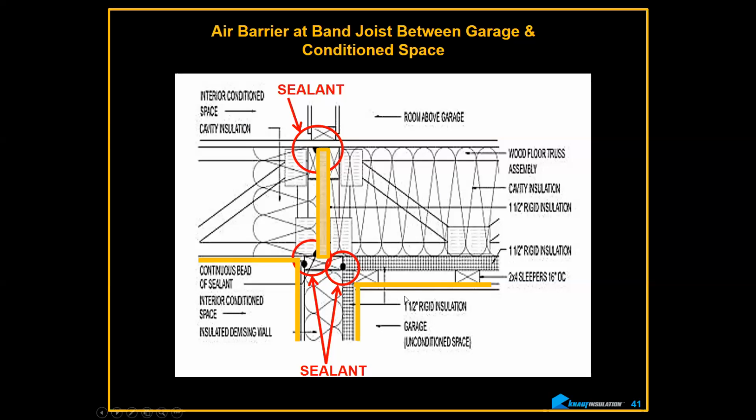Other thing I want to point out here that's very important. Let's say this is just a regular typical floor section here. There's a crawl space or an unconditioned basement below it. Here's your floor system, and let's call this the rim joist right here. So if you install this graphic of the insulation, everybody has seen this, I hope, and understands it. And remember, fibrous insulation is built up in layers to get the thickness that they need, so that air can wash across this in this direction, but not so much in this direction. It's slowed down. This is where the R value is calculated,